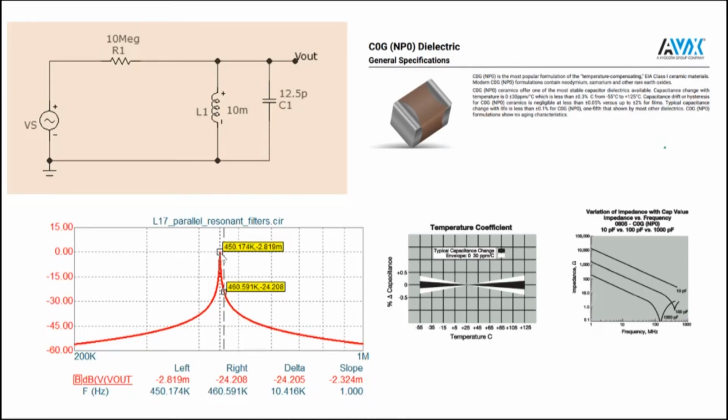And so as I'm saying, you may start off and switch on your radio and it's tuned to 450 kilohertz, and then after a while, as your radio heats up, you find that the signal fades away. Then, in olden days especially, one would fiddle around with the inductor or a capacitor, a variable inductance or capacitor, and you would have to retune the circuit. That is a problem, especially if you have a high Q circuit. A little bit of detuning of the circuit will cause a huge change in the output.